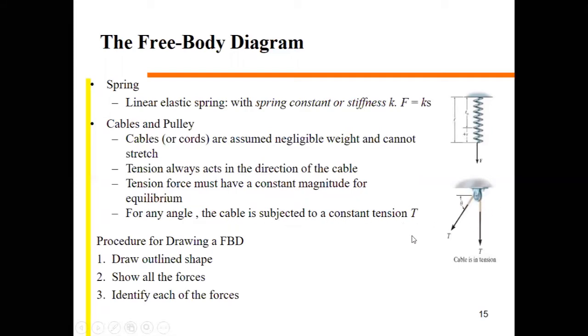So, how can we draw the free body diagram? Draw the outline of the shape. Show all the forces. Identify each of the forces with its direction. That's the main way we can draw the free body diagram.